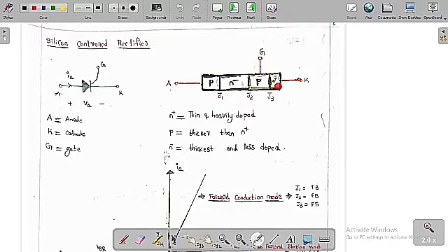You can see clearly here the anode, cathode and gate. This is junction J1, junction J2, junction J3. So SCR basically has 3 junctions and 4 layers. N plus means highly doped and N minus means lightly doped. N plus is thin and heavily doped; it is very thin in size, but heavily doped.